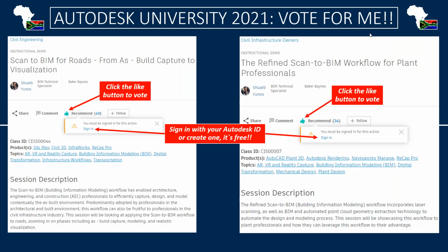But the only downfall with that is if there's any changes, you have to do it absolutely manually. That's not a good idea. It can be done, but it's not a good thing. Also, your positioning needs to be right, your geolocation needs to be right, your shared reference point. You also need to coordinate quite well with Infraworks, so that if you want to create a visual model, it lines up perfectly, it sits up to date, and everything is up to date. So you can see already there's a lot of manual process in there. Of course, if you manage it quite well, you can pull it off, but it's quite the longer route.